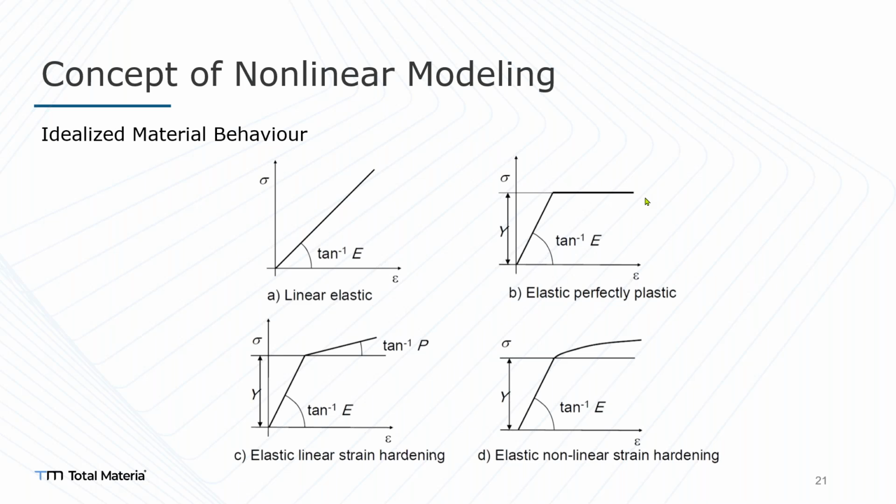So because of that, in order to avoid the convergence issues, you could apply slight hardening, really slight hardening, in order to solve that. But when you think about it, it becomes a bilinear model. So the bilinear model could be used, but it is up to you. It is because you're just simulating something to find out about the real world application.